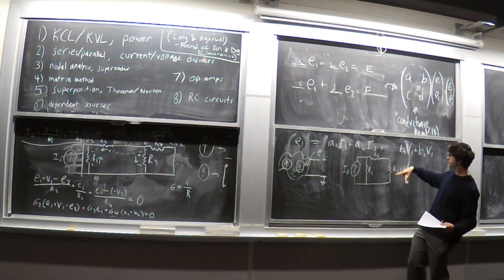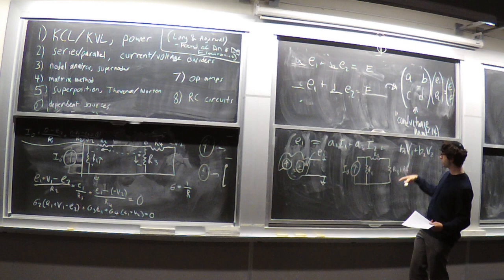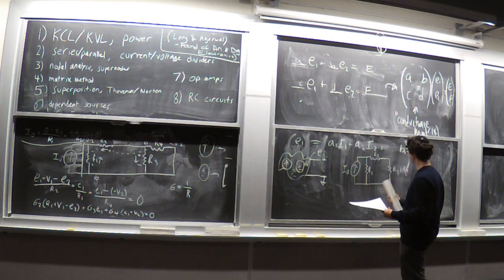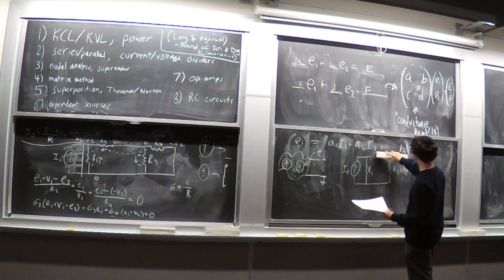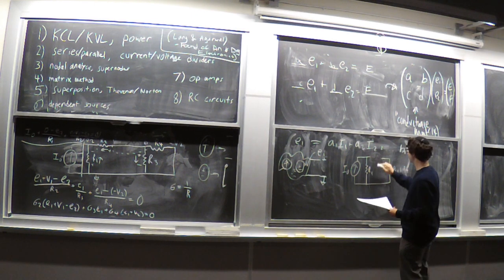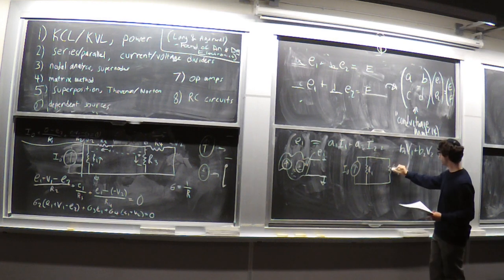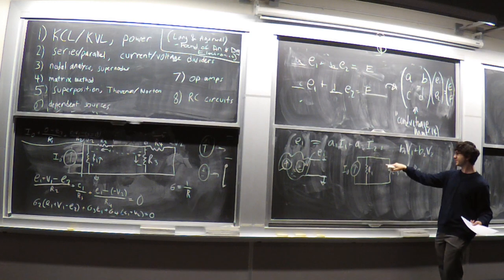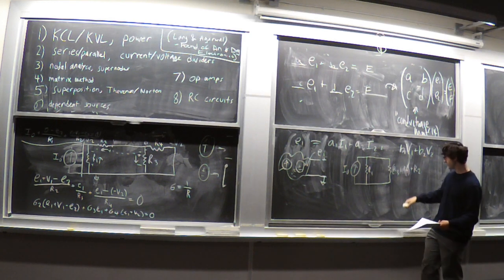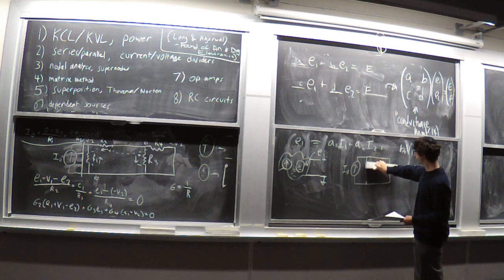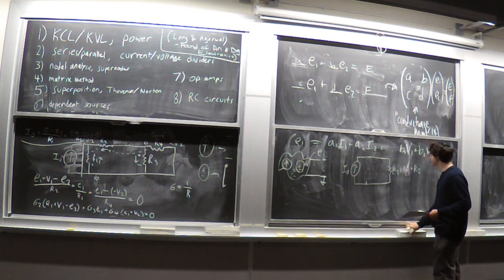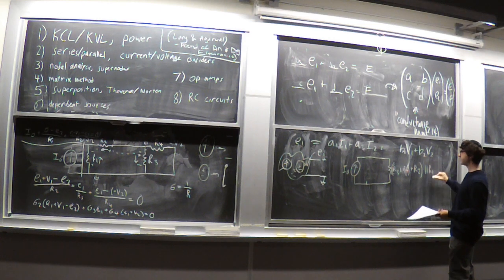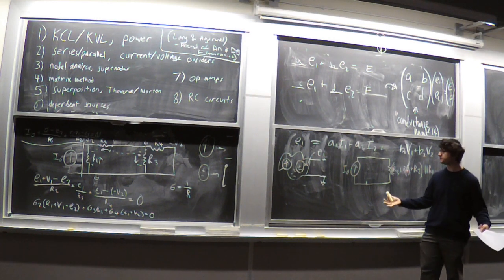And now these two resistors are in series, right, because they're just in this one branch. And so now we can replace that with a single resistor where we've added R2 into the mix. So now this just becomes this guy plus R2 since they were in series. But now, as you may have noticed, these guys are in parallel, and so now we can just get rid of this guy. Put that whole thing in parallel with R1, and now this is a very simple circuit.